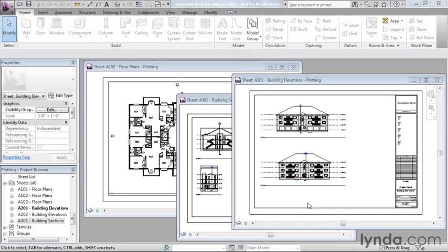The steps required to use the print command in Revit are not much different than what's required to print from nearly any Windows software. In this movie, we'll look at the procedure and step through the process, and look at the print dialog and the print setup dialog. If you need to print a PDF file, all that's required is an appropriate PDF printer, and you use the exact same procedure that we're going to show here. Just choose your PDF printer instead of your hard copy print device, and the steps are nearly identical.